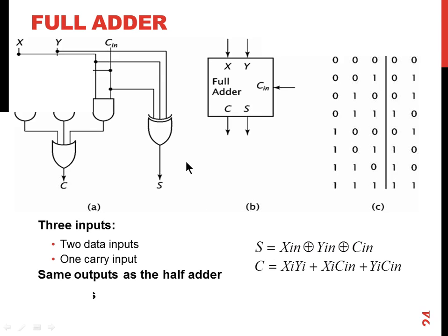The basic form of adder, now if you look at it, is a ripple carry adder. So here we have two inputs A and B. Each input is 16 bits, 15 down to 0. And an adder is represented for each bit of the input. So A0 plus B0 will be done by the 0th stage of the adder. And A1 and B1 will be added by the first stage of the adder, and so on till the 15th stage of the adder. Each stage of the adder has two single bit inputs, one carry in input and two outputs, sum and carry out for that stage.